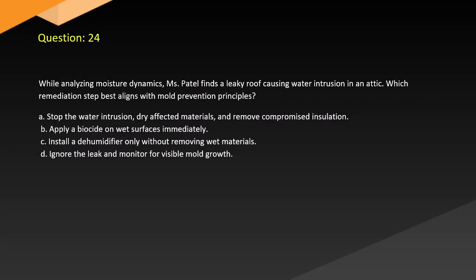Question 24. While analyzing moisture dynamics, Patel finds a leaky roof causing water intrusion in an attic. Which remediation step best aligns with mold prevention principles? A. Stop the water intrusion, dry affected materials, and remove compromised insulation. B. Apply a biocide on wet surfaces immediately. C. Install a dehumidifier only without removing wet materials. D. Ignore the leak and monitor for visible mold growth.